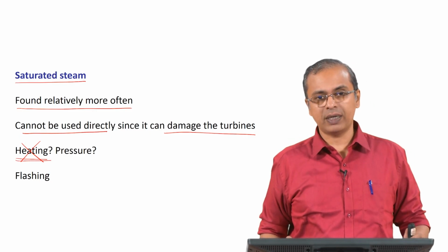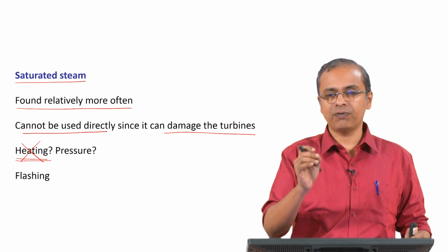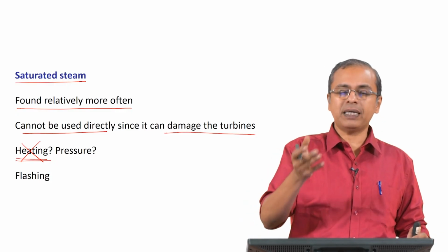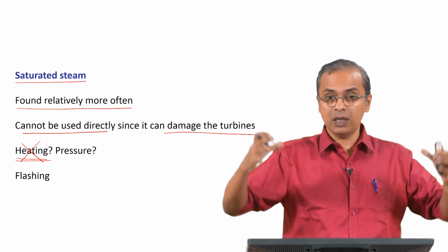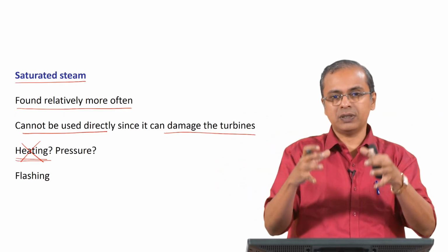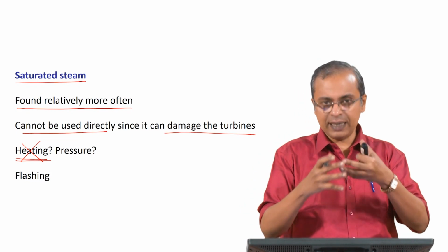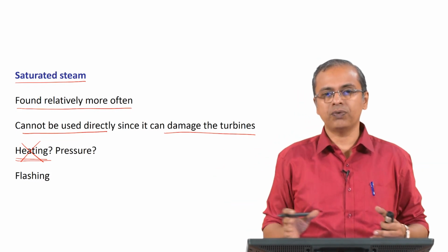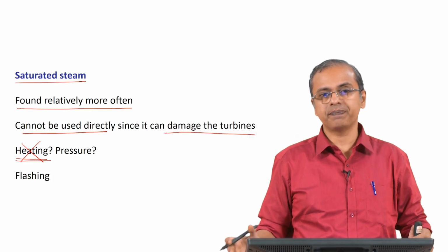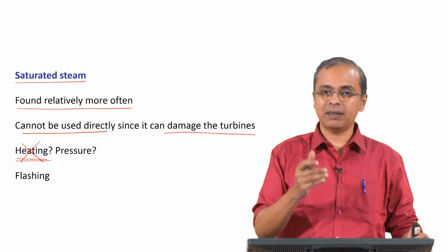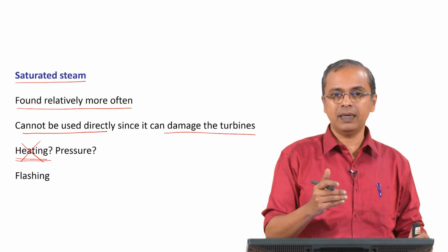I told you that if you have a melting point for a metal and you increase the pressure, you can go to an even higher temperature and the metal will still not melt. It will stay in solid state, because you have put pressure to force those atoms to stay together, and therefore it is unable to melt. The idea of melting is that they have drifted away from their crystal structure and are moving around, but because of pressure they are now staying together. So, at high pressure the metal does not melt as easily as it melts at, say, 1 atmosphere pressure.